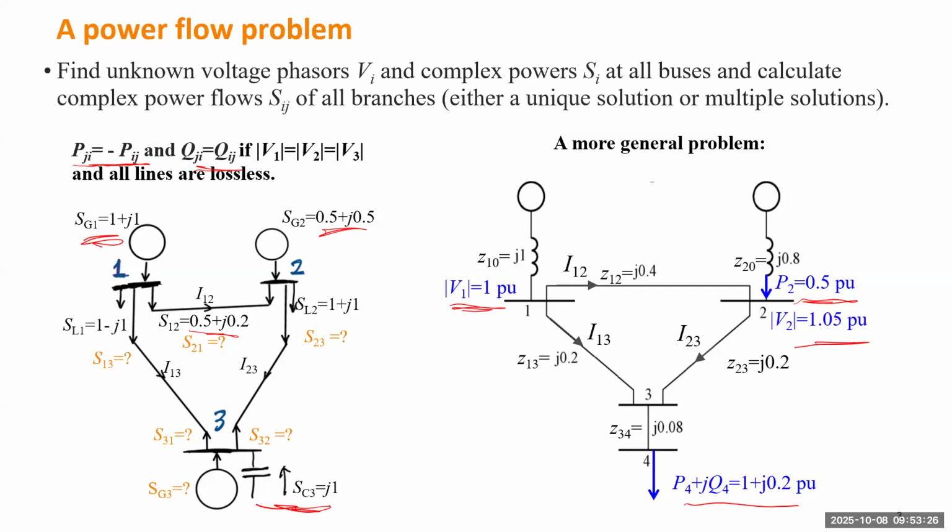The objective of power flow is to solve for each bus in this figure, no matter which type they fall into. For bus 2 we need to know the Q and the angle, for bus 4 we need to know the voltage and angle, and for bus 1 we need to know the angle, P and Q. Actually, there's also bus 3, right?